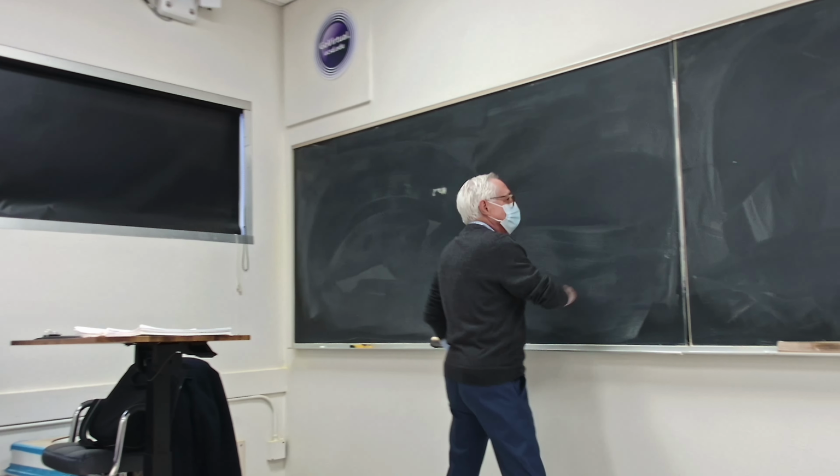Let's say if this is, say, I don't know, 20 bar, you drop it to 5 bar, right? Find this state. What do we do? The only thing we have is h1 equal h2, right? Therefore, you know your h2. You go to the saturation table at 5 bar.